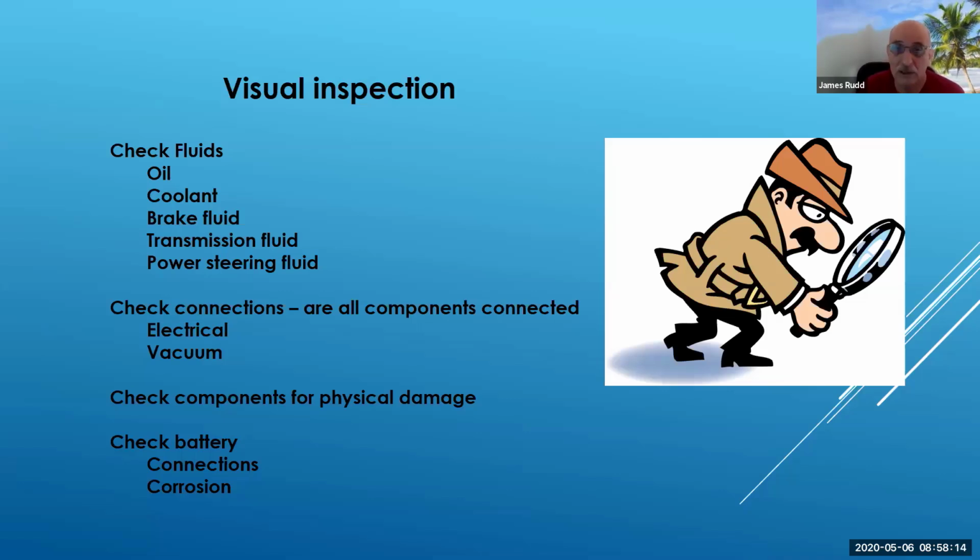I'm also looking at the brake fluid, because I want to make sure I make it around the block. Especially when it comes to performance, I will go around the block in the car. If it's a strange problem, I might even take the customer on the ride. I'm looking at the transmission fluid. This is mainly on the automatics, except for the ones that do not have a dipstick. Then you don't really have the ability to do that.